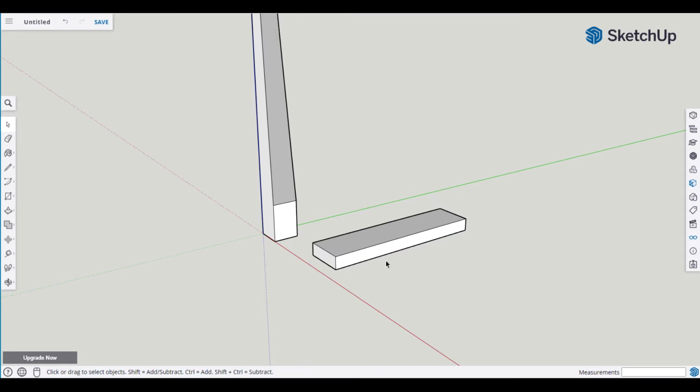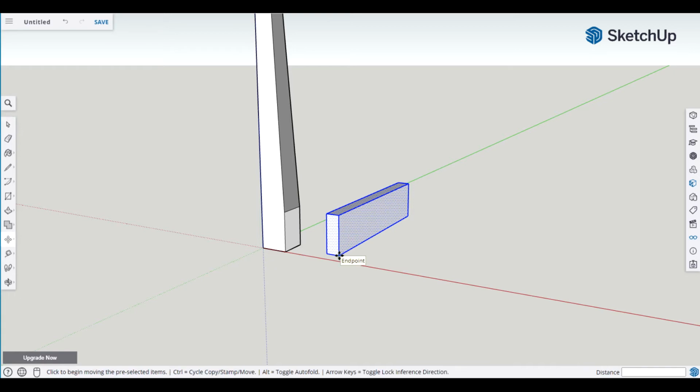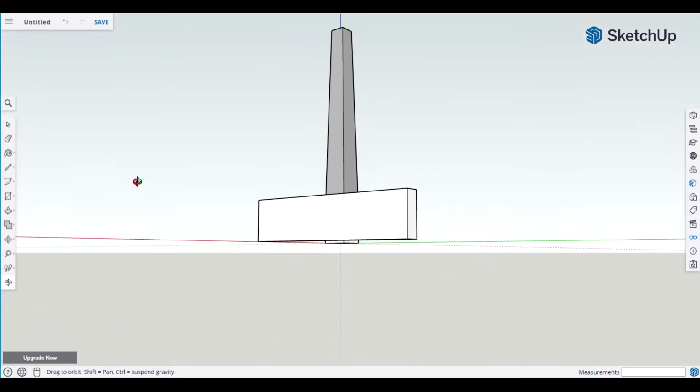That's good so far. Next, we're going to triple click, and we're going to flip this now. We're going to rotate it. I'm still not going to make it a component because we've got to do a couple things to it. So let's hit Q, and we're going to put it on the green. So left arrow key, click, rotate up, type in 90, good. And then let's just move this a little way out of the way so we can deal with it.